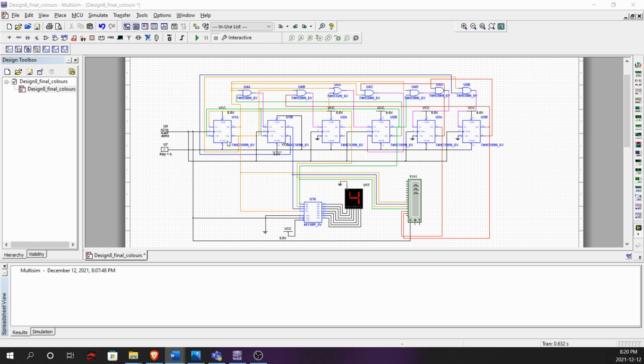As you can see here, the flip-flop outputs are then connected to the decoder chip, which is then wired to the 7-segment display. The blanking pin on the decoder chip is also connected to the clock, which means that the display will turn off in between numbers. This should make it easier to ensure that successive digits are getting repeated the correct number of times.